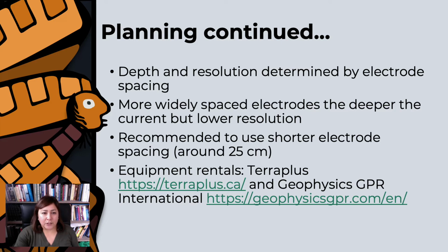Regardless of the variation in data collection, how you design your survey will depend largely on the equipment you have available. It is also important to remember that resistivity is helpful in cases where other geophysical techniques, such as GPR, fail. Notably, resistivity is a reliable technique in high clay or saline environments and in areas with lots of obstructions and vegetation, environments that typically prohibit the use of GPR.